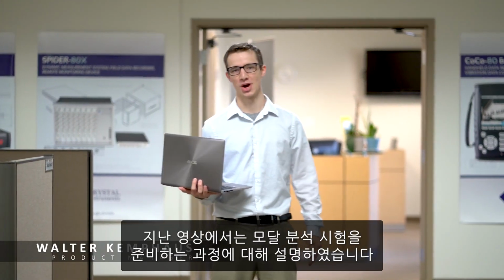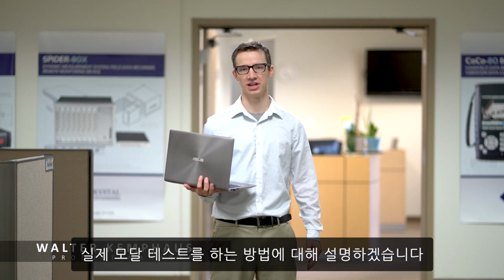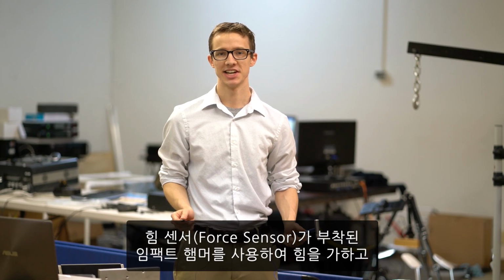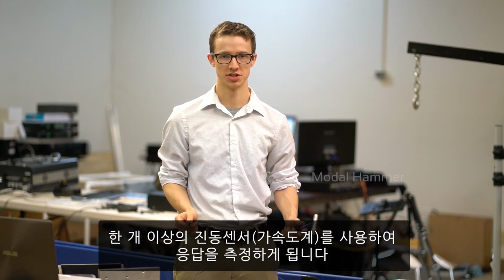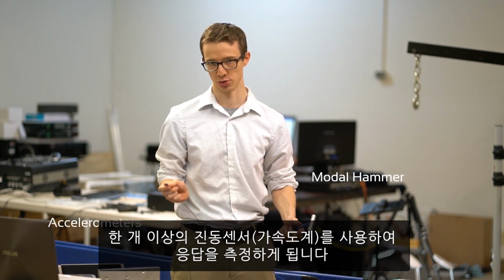Last episode we showed you how to prepare a modal test. In this episode we're going to demonstrate how to acquire modal data using hammer impact. Hammer impact tests are typically done with a force sensor, such as a modal hammer, to measure the excitation, and one or more accelerometers to measure the response.